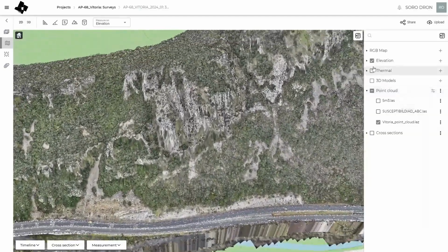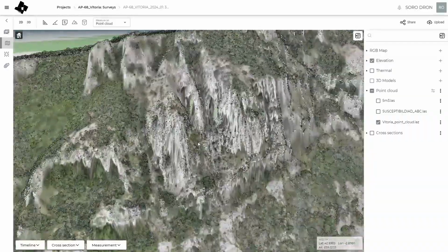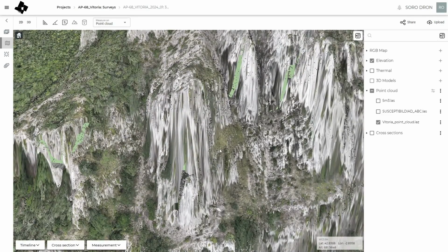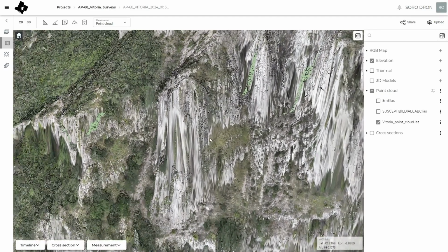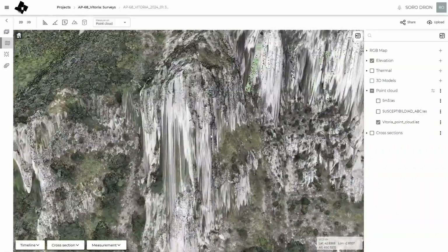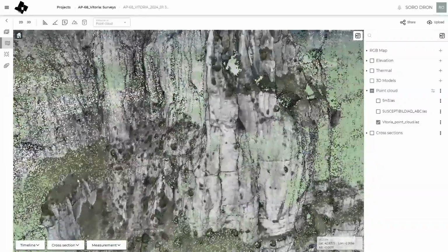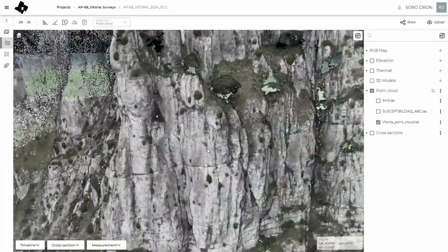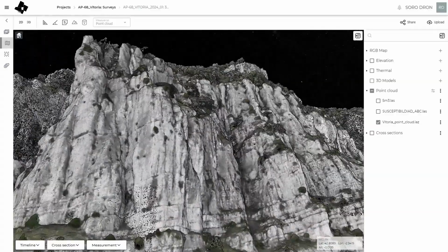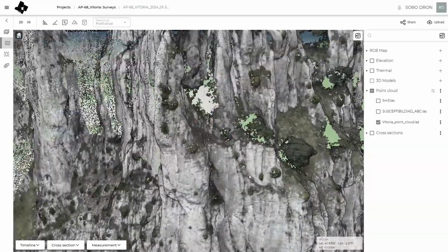So for sure we can check this beautiful 3D point cloud that we can get with Mavic 3 Enterprise with RTK, or Matrice 350 RTK with a P1 camera, or from LiDAR, or another kind of tools using photogrammetric reconstruction or LiDAR tools. In this way, we can get extra high quality point clouds of a cliff, and we can use all this data in order to characterize the joint patterns of this rock massif, and also to identify the potential unstable volumes.